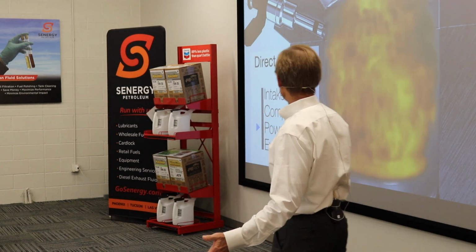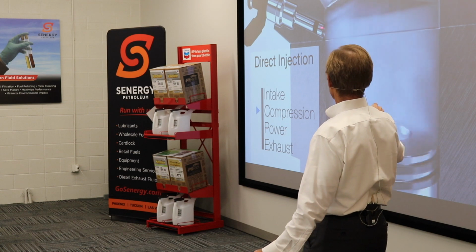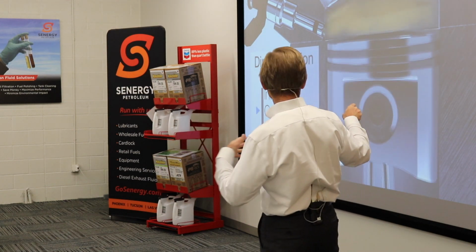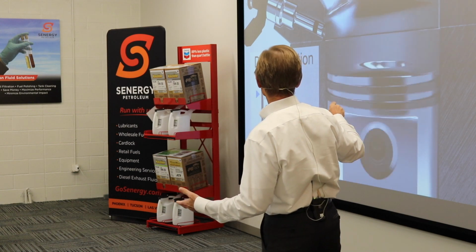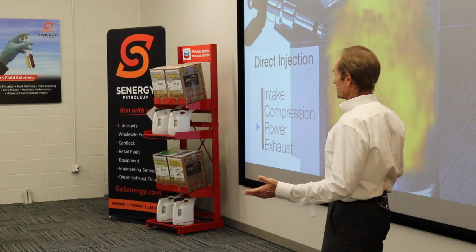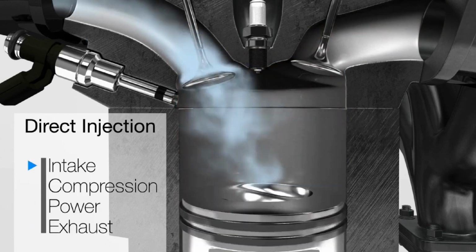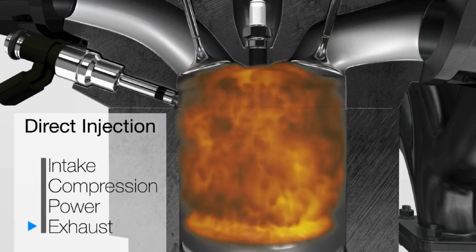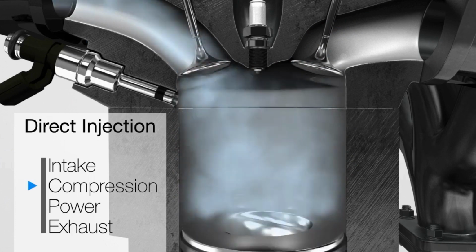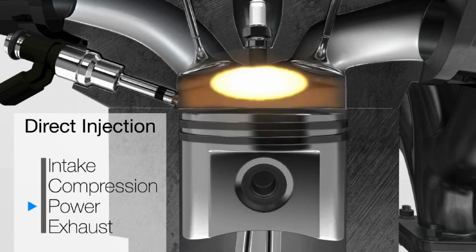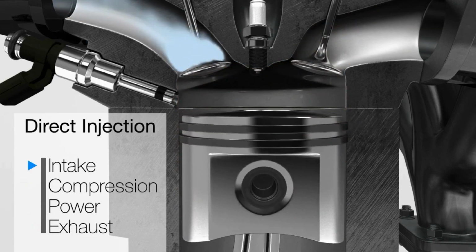And so the next thing is the direct injection, right? Our injector, like a diesel engine, is shooting directly into the combustion chamber. Okay? All right? So that's, again, gains in horsepower, improvements in emissions, but it makes life a lot tougher on a number of factors in the engine.